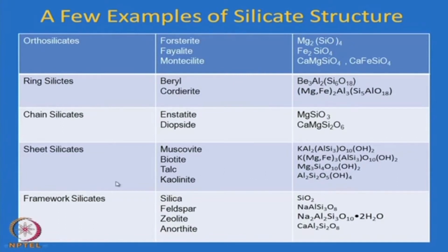So, these are talc, basically hydrated magnesium silicate. Kaolinite is hydrated aluminum silicate, and this is a symmetric structure, one layer of silica and one layer of aluminum hydroxide. Here, two layers of silica and one layer of magnesia instead of aluminum. If you put magnesium in a very similar structure, so just replace aluminum by magnesium, you will get talc. And then these are biotite, which are mica-based or mica-like substances, and muscovite is actually mica.